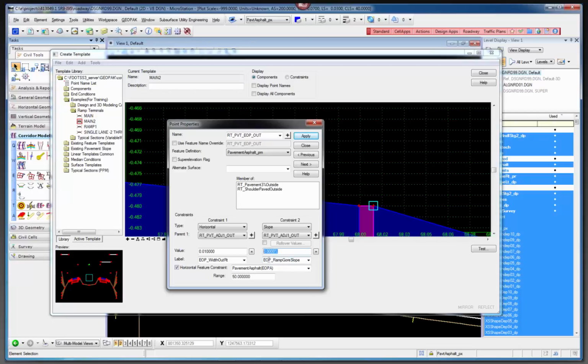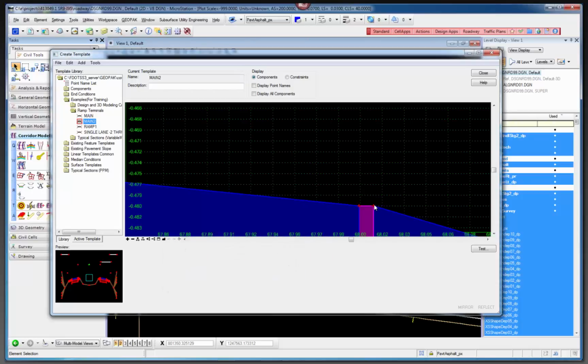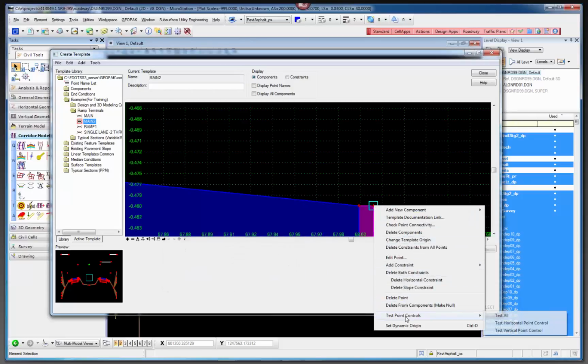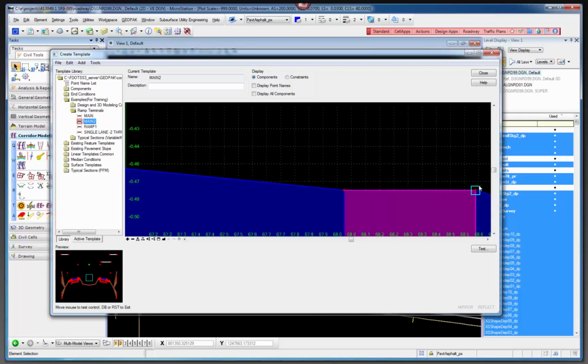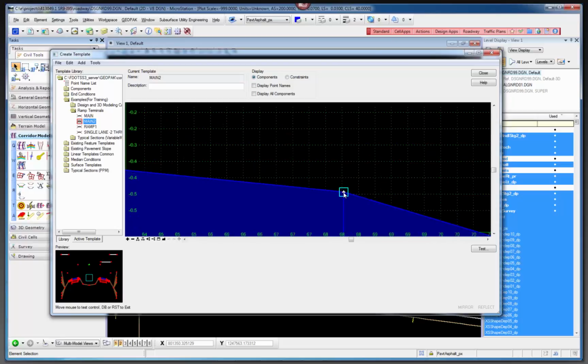You could do that as a parametric constraint. But essentially it's going to use the other part of that Gore line, the taper back into the edge of pavement, to essentially take this from being out here at, I think it's 19 feet or 12 feet or whatever it is, to where it transitions back in and has a normal shoulder.